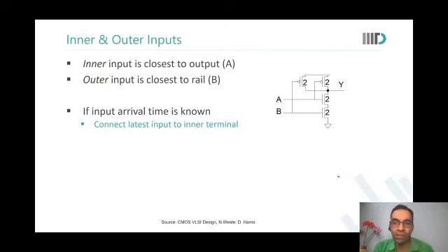You want the delays to reduce in a path, na, Raghav? Okay, we have graduated from characterization to designing. Now we are ordering the inputs such that we get the least delay in my path. Like for logical effort, the intent was to get least delay and least area in the path. The specification will also specify how the signals are arriving. For example, if I ask you to make an adder, you will know which signals will arrive first and which will arrive late. You are a designer. It is not about designing one gate, it is designing a path.